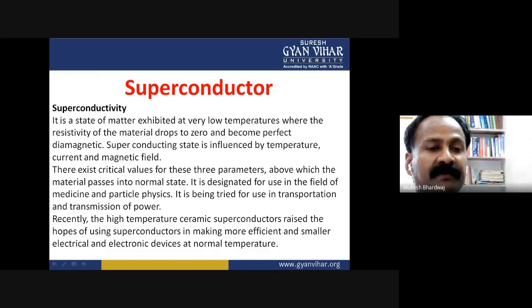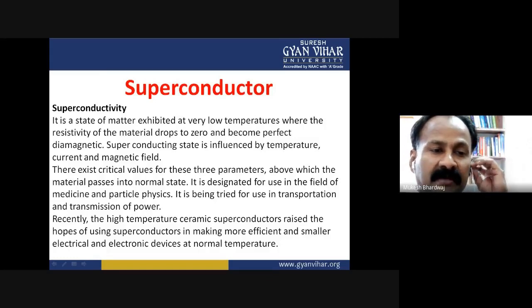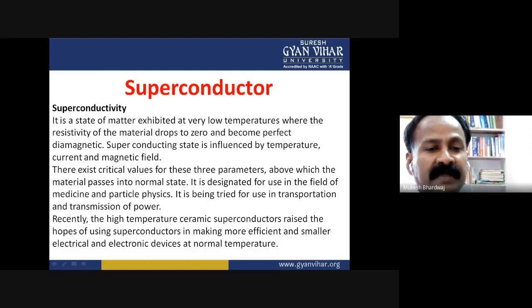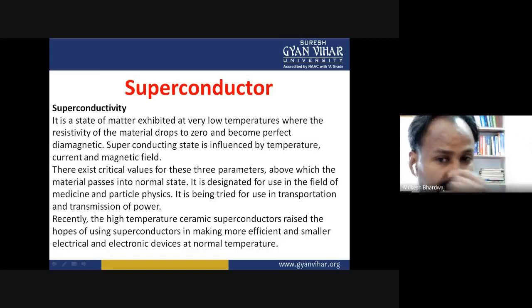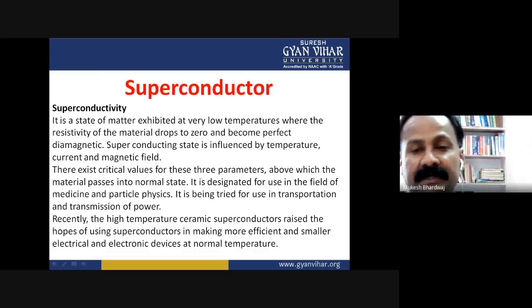The preparation of intrinsic silicon is less difficult than that for germanium because more impurity ions can be tolerated in states within the energy gap, because of its wider energy gap, before it shows extrinsic behavior. Silicon is used for the majority of rectifiers, transistors, and integrated circuits.